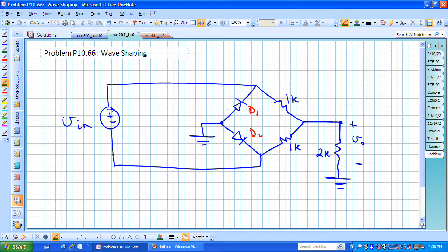And all of that refers to the anode end of the diode and the cathode end. I've come to learn that sometimes the cathode is referred to by the letter K. For this diode to conduct, we would need the anode end of the diode to be more positive than the cathode end, and we'll get more into that as we work through this problem.